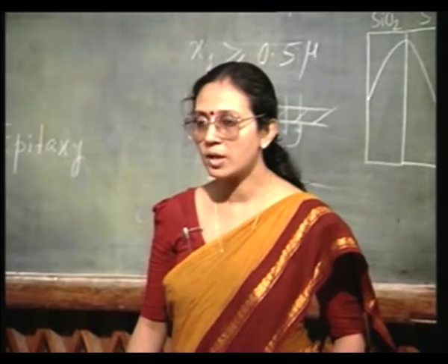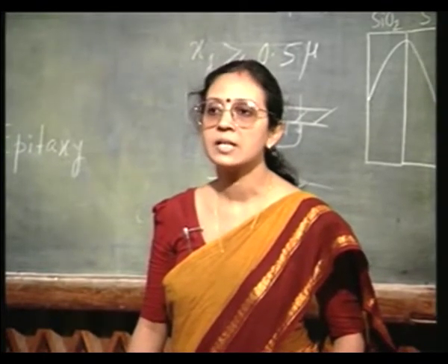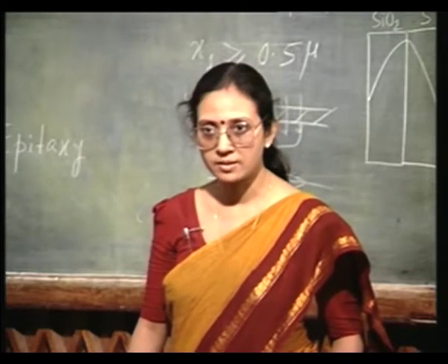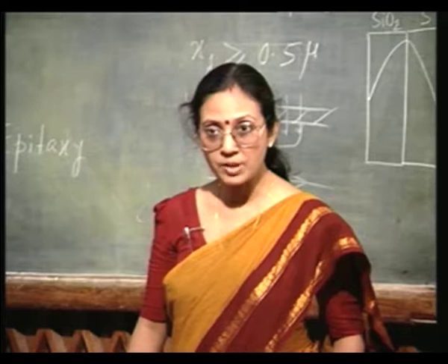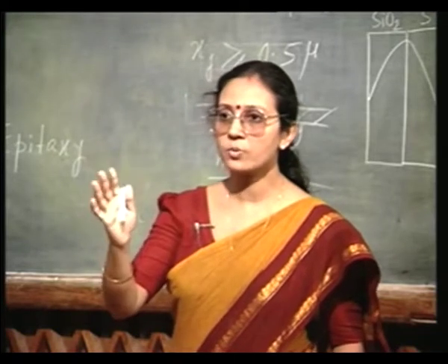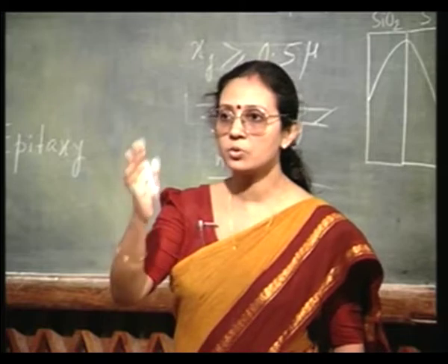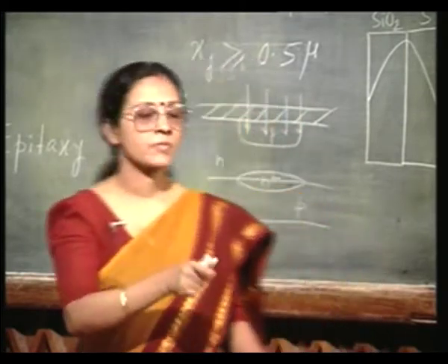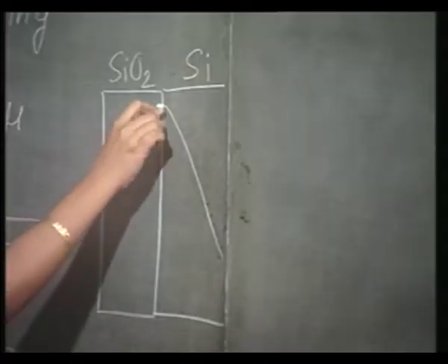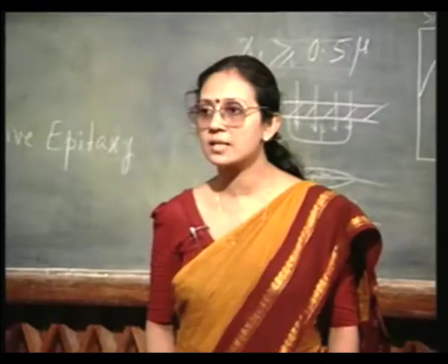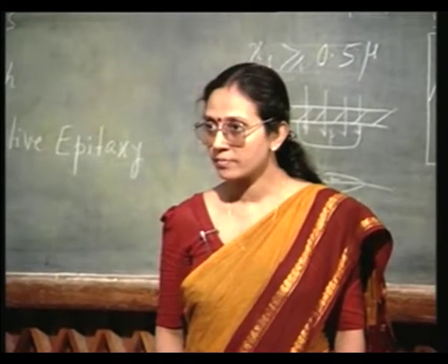The peak of the implantation signifies that region where most of the ions are coming to rest. That is the peak in very crude terms. In a Gaussian distribution, the peak is where most of the ions are coming to rest, that is the average. So, the damage peak is actually just before that, when most of the ions are still in motion, and that is where it is creating maximum damage.